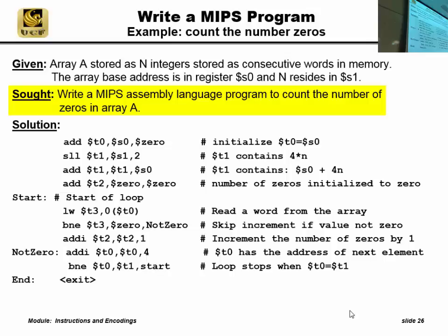So if somebody's giving you a data file or there's an antenna, because it's your job to interface this antenna, you want to know the percentage of the signal which is below some threshold. In this case, the value is 0. There's no signal coming in. You want to add up that percentage. You're going to count the total number of samples that are 0, divide by the total number of samples you saw, and that's the percentage of time that there's no signal. Is that easy? Well, yeah, that's what the specification is.